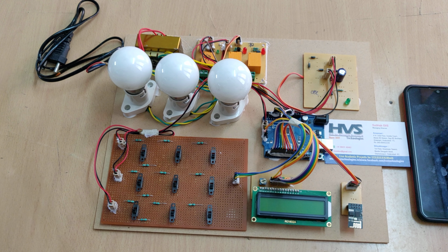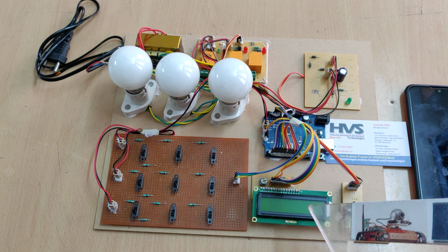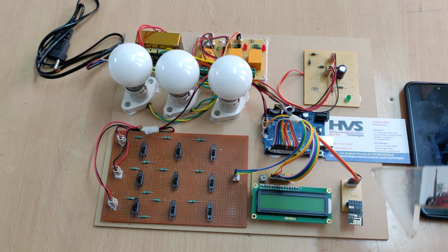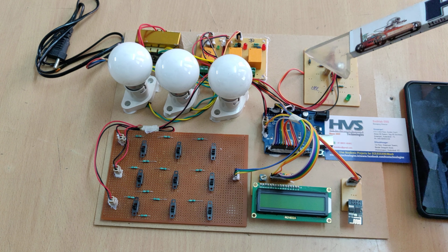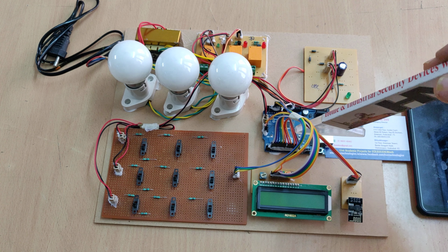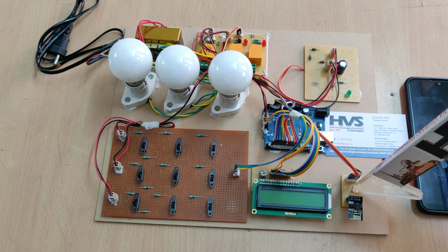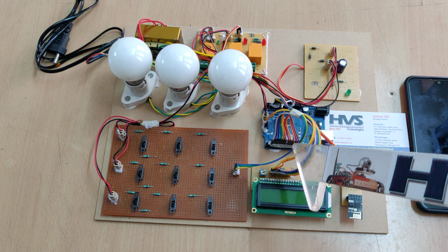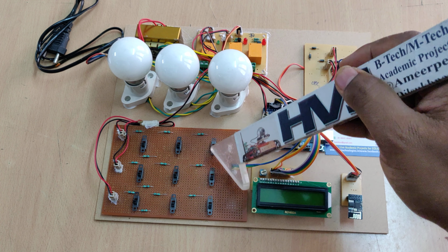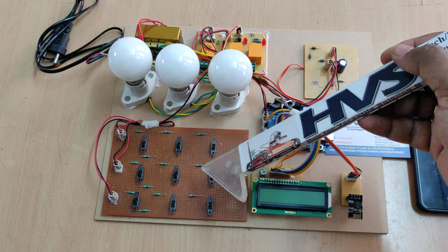From this Arduino UNO board we distribute the 5 volts power supply to this LCD module as well as to our ESP8266 module. Coming to the interfacing connections, we have interfaced the electromagnetic relays at pins 10, 11, 12 of our UNO board, pins 8 and 9 for the ESP8266 module, pin 2 to pin 7 for the LCD module, and A0, A1, A2 pins for the respective phases to measure the input